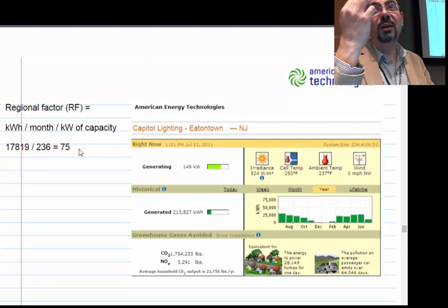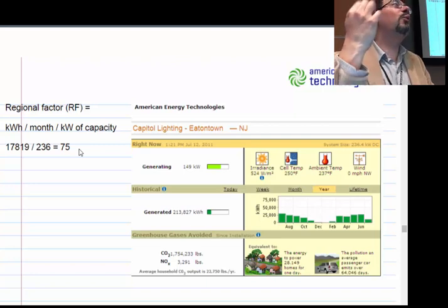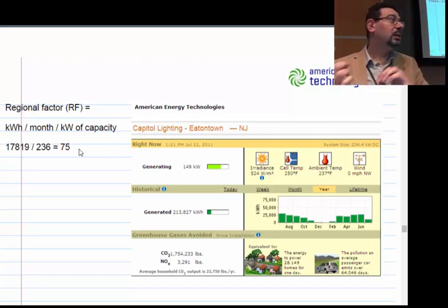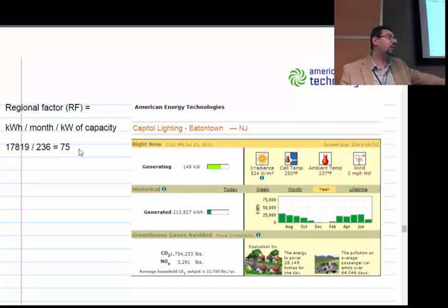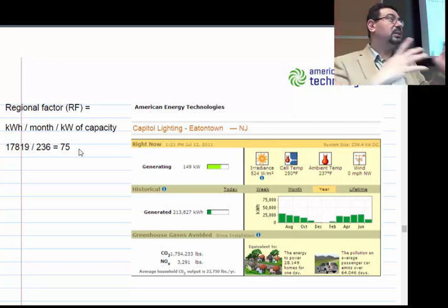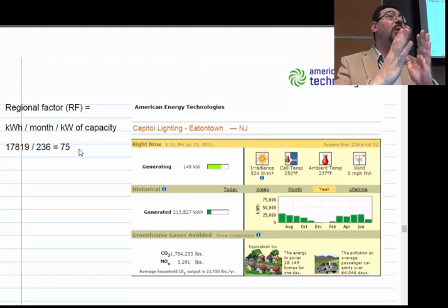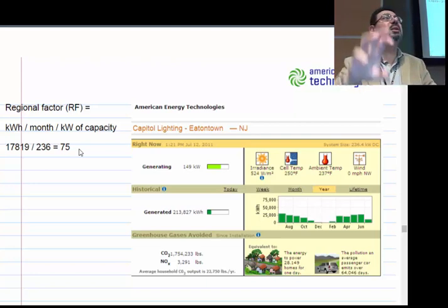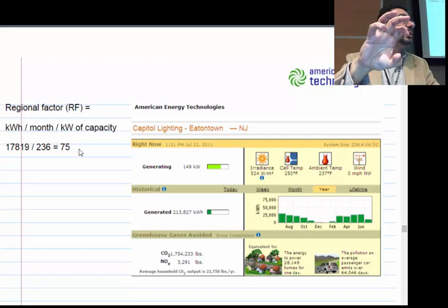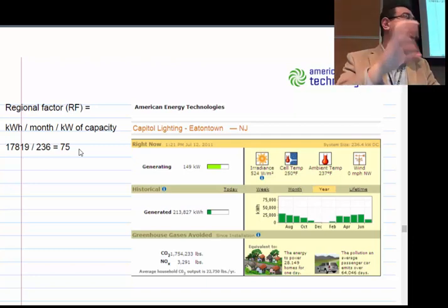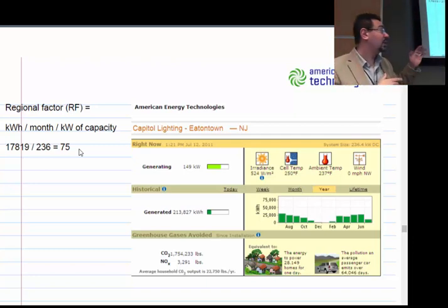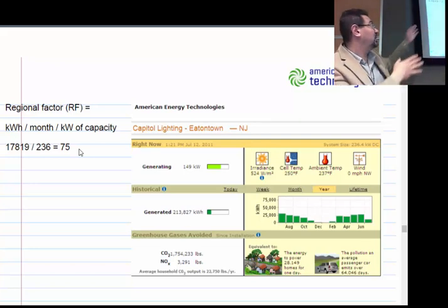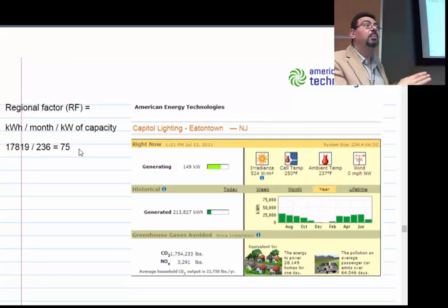No. You get 75 hours of one sun. The sun, so you are all focusing on the output. It's the input. It's as if you get 75 hours of one sun. The sun is radiating at 1000 watt per meter square for 75 hours during this month. And for the rest of the months, the sun is zero.